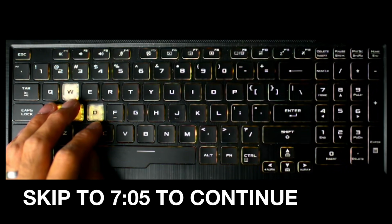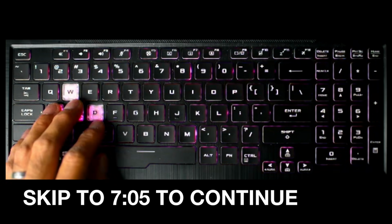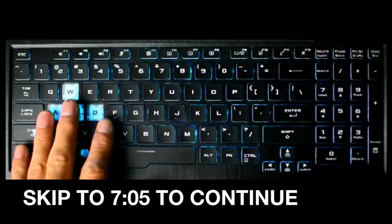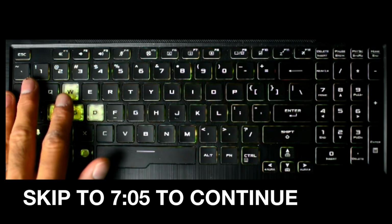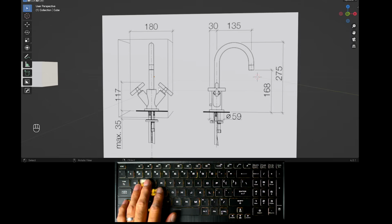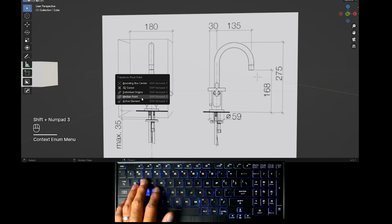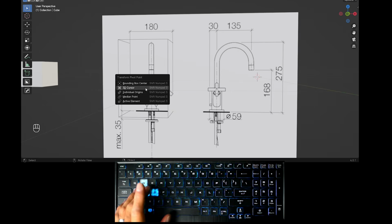That can be very helpful with shortcuts. I try to keep a lot of my shortcuts all right here on the left side of the keyboard, so I don't have to significantly change the position of my hand on the keyboard often. So from this hand position, Shift 3 now brings up the Transform Pivot Point menu, and the common shortcuts that I use here often are B for bounding box and D for 3D cursor.